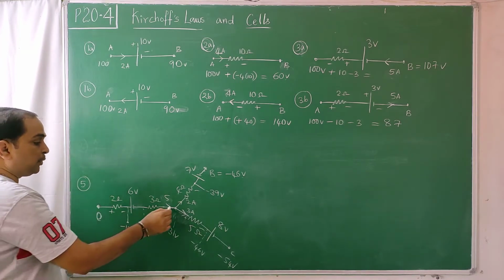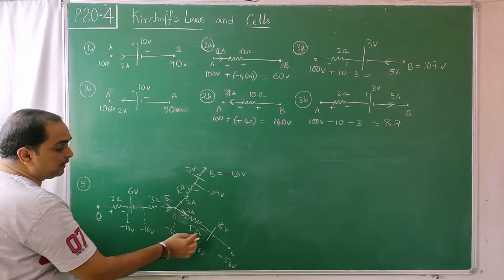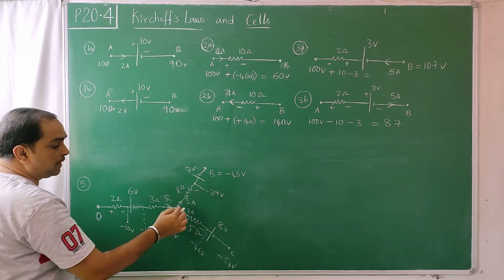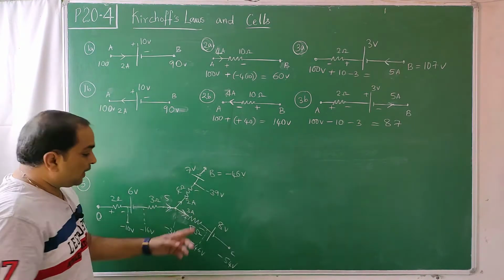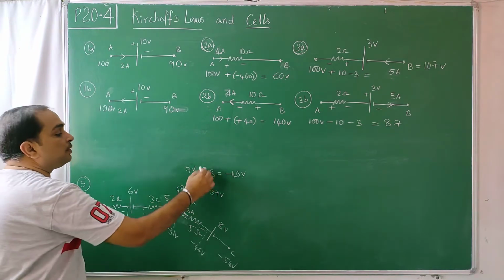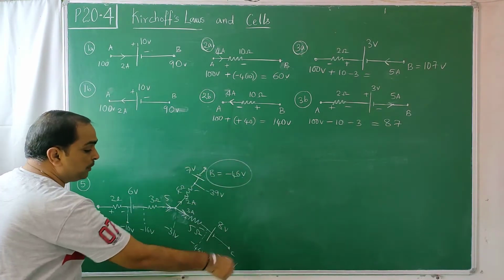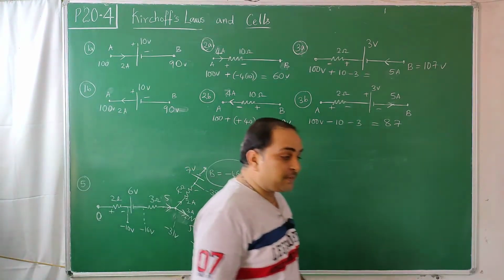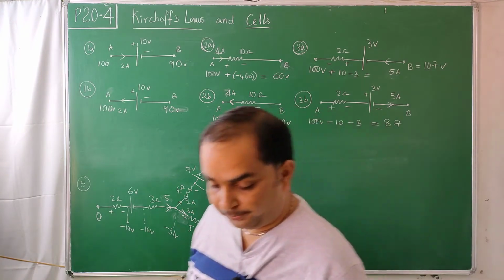Accordingly, if you write it, then the potential difference 31 minus 16 by 3, you will get this current. 46 minus 31 by 5, you will get this current. 39 minus 31 by 4, you will get this current. And these currents are governed by, this should be kept at minus 46 by the battery on that side. This 54 should be maintained by some other battery. This 0 should be maintained by some other battery. So it's a part of a circuit, not the total circuit.